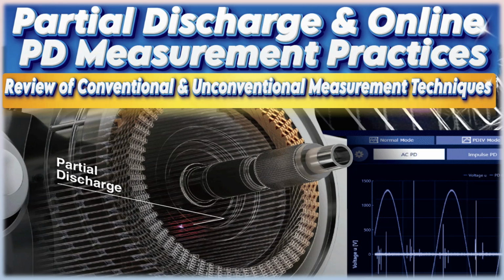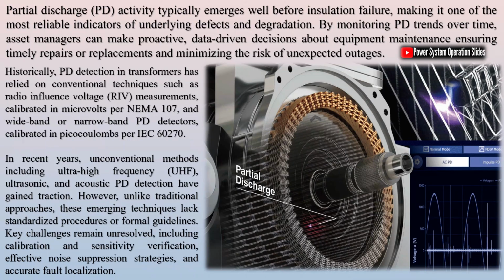Partial discharge (PD) represents a localized electrical breakdown phenomenon that occurs in insulation systems under high voltage stress without completely bridging the insulation. This phenomenon serves as one of the earliest and most evident indicators of insulation defects and deterioration, making it a critical parameter for condition monitoring of high voltage equipment.